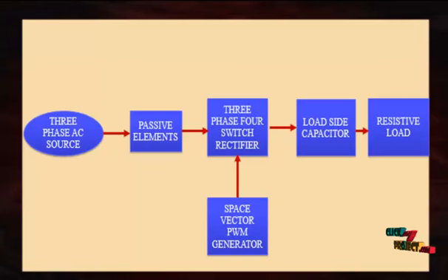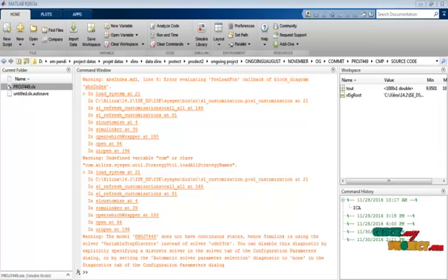The simulation output is compared with the 6-switch PWM converter, and the result shows that a higher output voltage is obtained in the 4-switch PWM converter when compared to conventional methods. It also proves that the 4 switches with the proposed switching schemes function successfully with the real-time controller, and it is used for real-time control of power electronic converter constraints, which is widely used in industries. It is also used for induction motor control, and drives induction motors and other kinds of AC motors. Next we see the running process of our product.